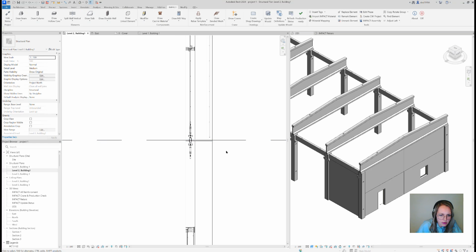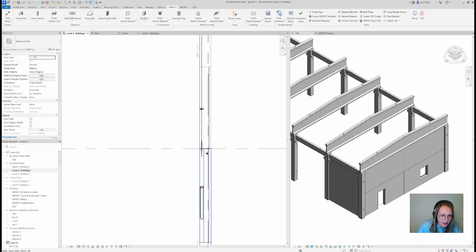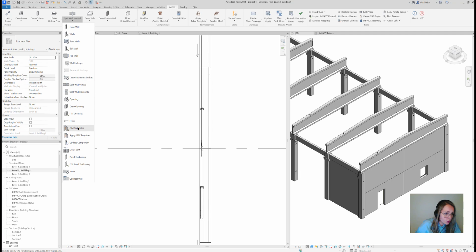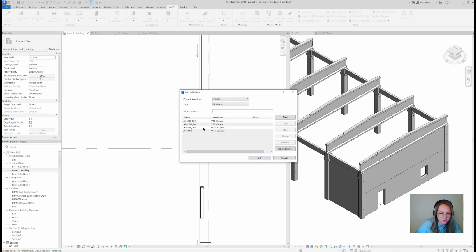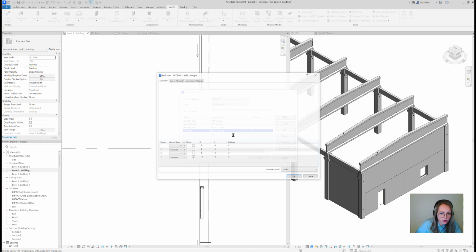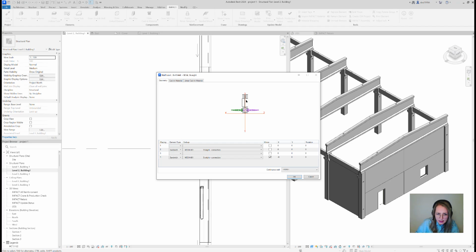So instead of applying in cap and then casting material templates like we did, that's one option, and that's okay to do it like this. But there's an even more powerful tool for detailing, and that's the joint. Basically, let's take a look at this one. What you're having in the joint is in cap, end geometry, spacing between the walls, gaps, and inserting of casting materials in one.